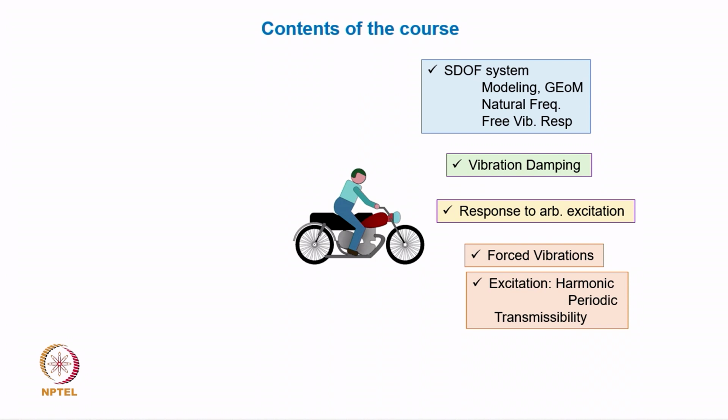So, we extensively analyzed the response to different ways of harmonic excitation. The excitation could come from the force acting on the inertial mass, or the force could be through the base excitation or a base profile or a base motion. In either of these 2 cases, we explored how the response is obtained for a given excitation frequency.